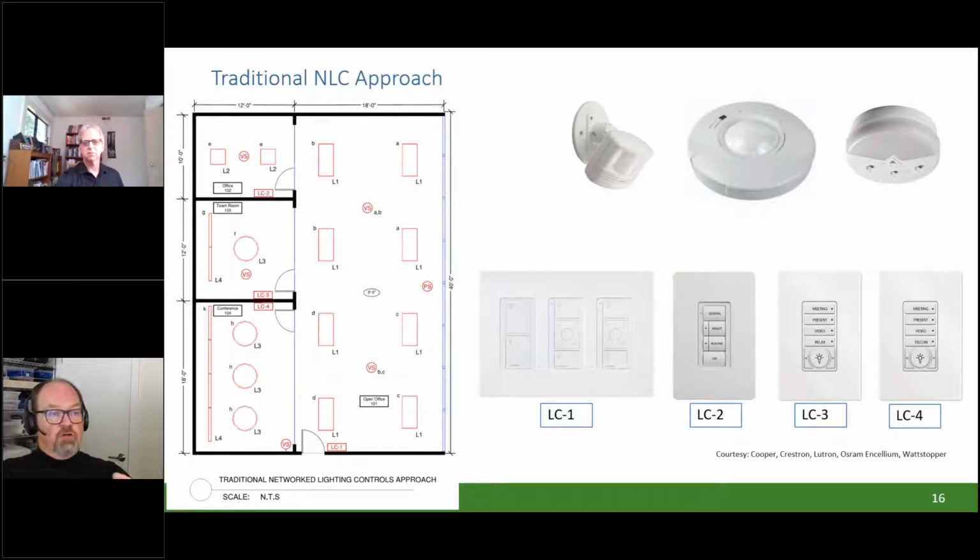As long as all of the zones that you're controlling are facing east, then you can control the primary and secondary daylight zone from one sensor. Effectively, what it will do is a little bit of a percentage algorithm, so that the primary daylight zone will dim by a certain percentage. The secondary daylight zone will dim by another percentage, right? So essentially you have deeper dimming closer to the window, and less dimming a little bit further from the window. That's how a lot of systems are set up and configured.